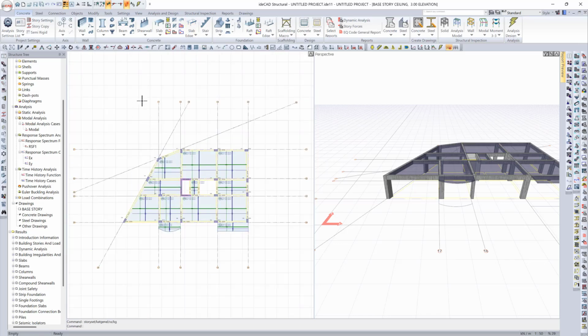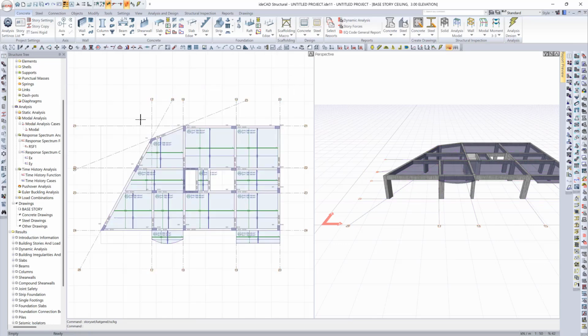Now that we have defined the axes, shear walls, beams, and columns, we can define the other stories and copy the current story to them. But first, we run a contour calculation to automatically generate axis deltas. To do this, under the Axis command, we click Calculate Contour. Then, since the imported DWG base was brought in as a block, we can now select and delete it from the model. After removing the base drawing, click the Story Settings command.